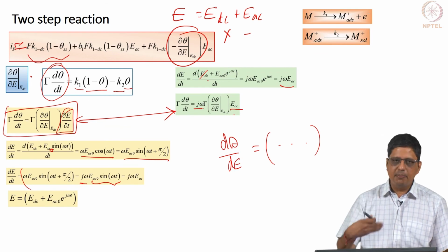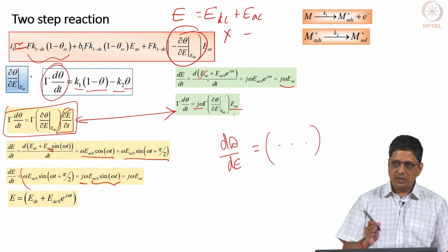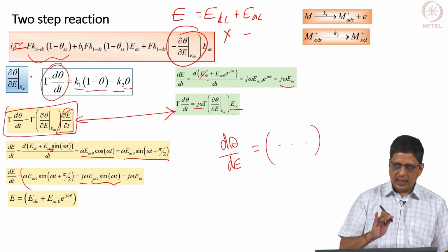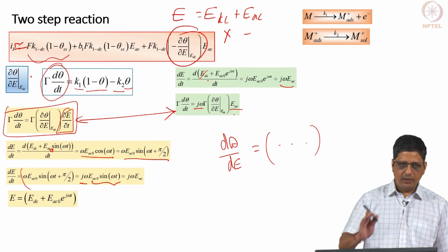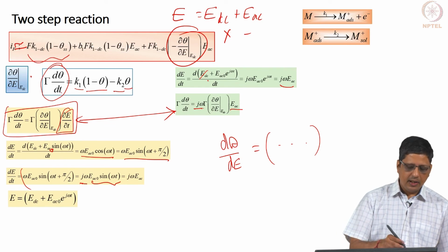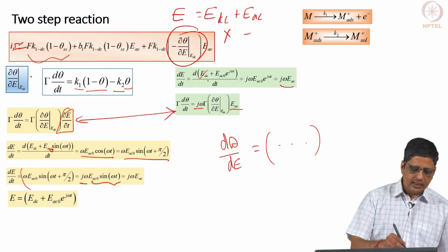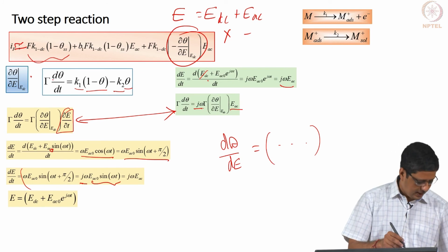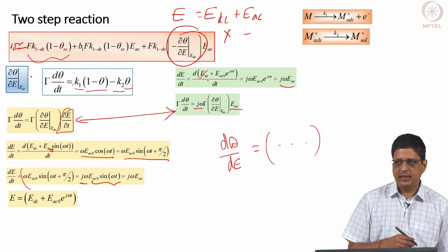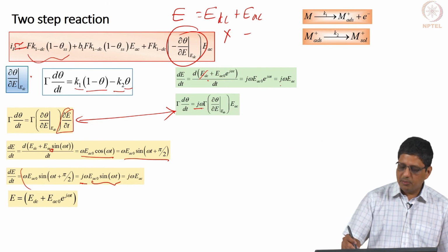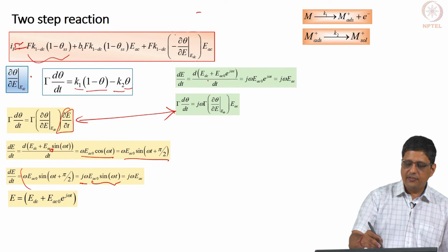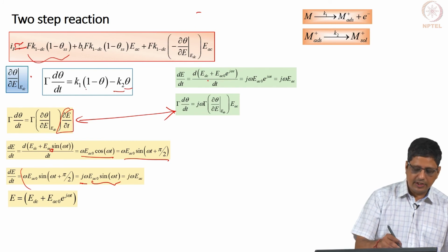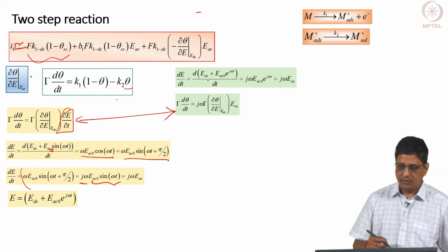It may need 10 pages of derivation, but it is not going to take anything more than writing in Taylor series, chopping off after some term, doing some algebra and recognizing this mass balance equation, the left side of this equation can be written like this. And of course, remember all these are applicable when we say mass transfer is very fast. This is a mass balance equation, right, not mass transfer equation.